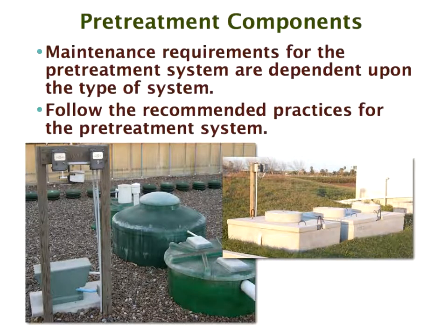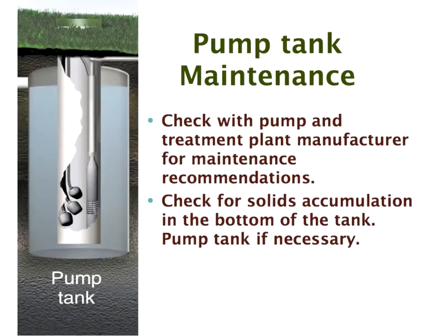Okay. Now, pre-treatment, of course, has to be maintained. And this is, of course, up to the recommended practices of the pre-treatment manufacturer. We don't, obviously, make any recommendation on that, but they have to be maintained. If they're not maintained, obviously, the drip system filters are going to plug, and then, as I said, the homeowner can come along and take out the screen, and again, 5, 6, 7 years later, the whole system's plugged up and I can't get it clean.